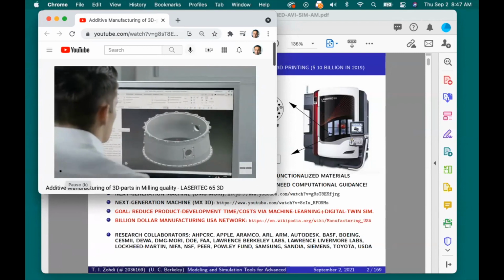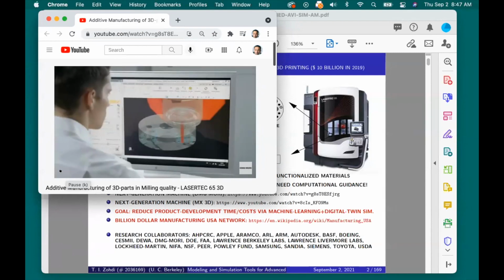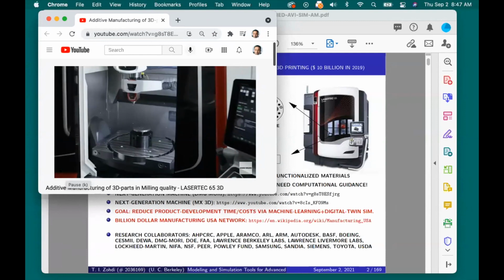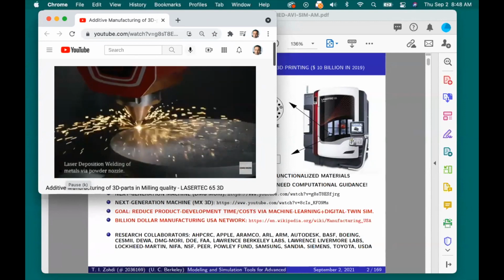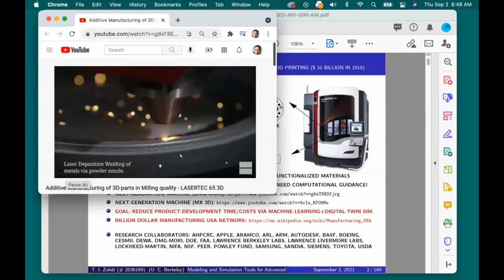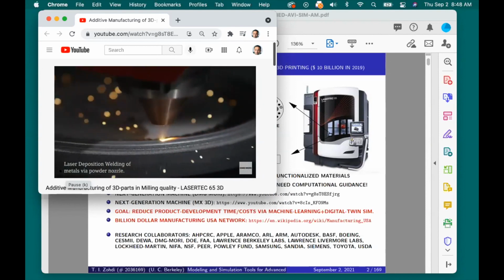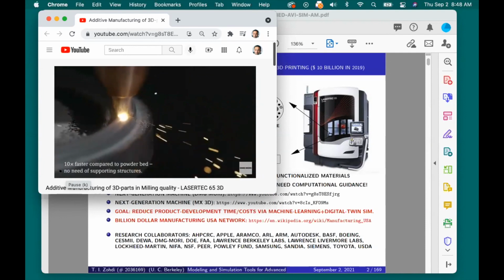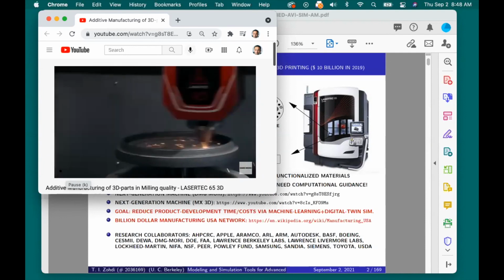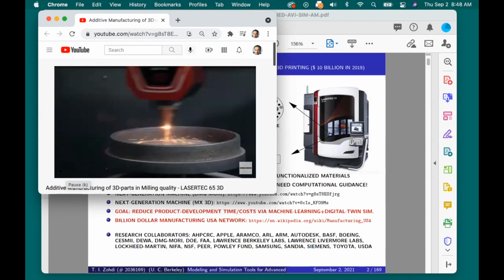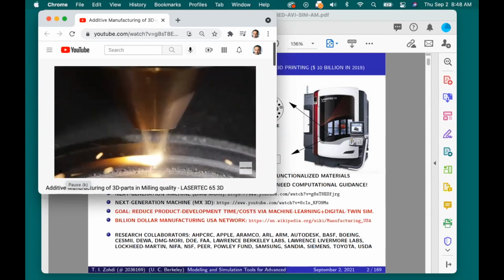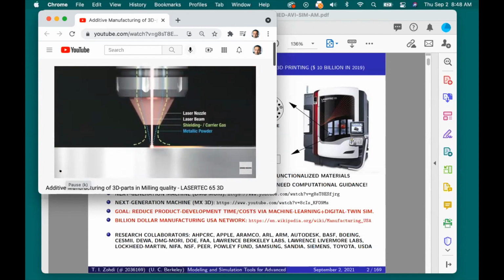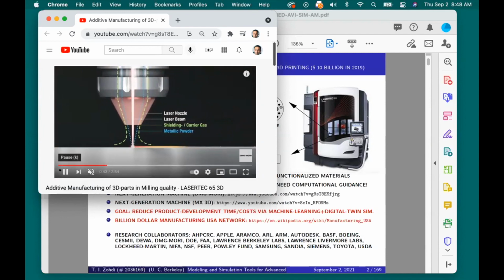It was a prototype in 2015. They primarily take STL files. These machines then deposit powdered titanium, iron, a variety of different materials. The material is entrained in an argon jet. It's powdered. You can see there's a lot of material waste, huge residual stresses. It's operating roughly at about 5 times the actual speed. This is important, this section here, which is essentially spot welding the material on contact.